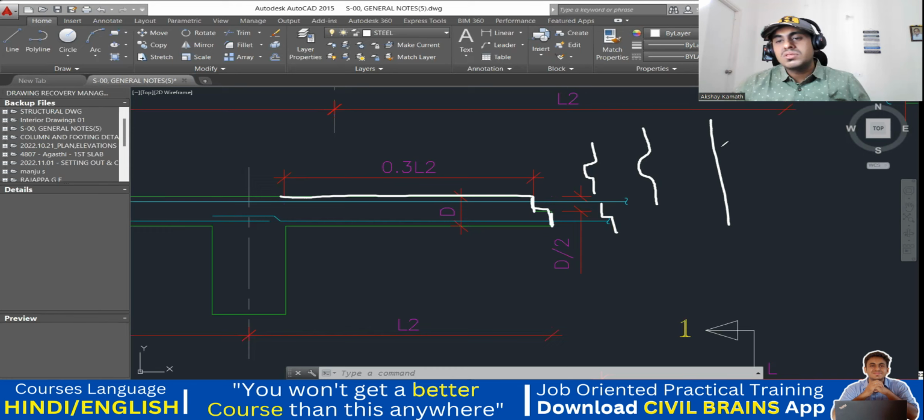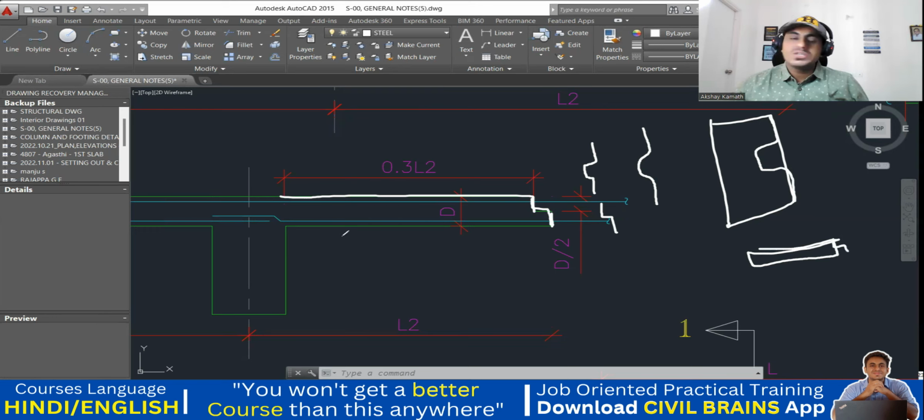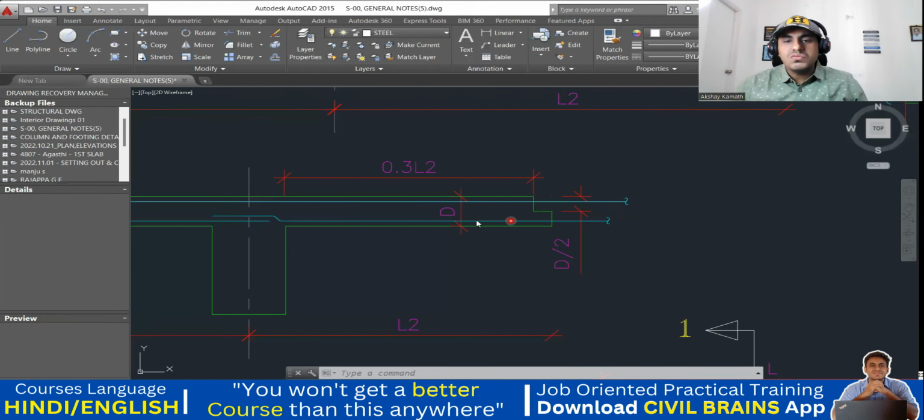So since it was a 600 mm beam, you could have easily stopped like this. You had enough gap, you could have stopped like this. In case of slab, your slab thickness is only this much, 150. So what you'll do? You make it in only two steps. You bring one step and second step. Understood? So that is why, since slab thickness is small, we are doing like this. And that's it. That is enough.